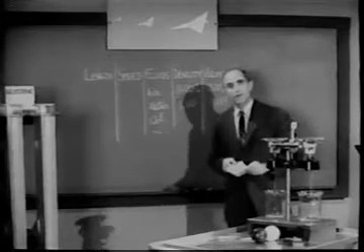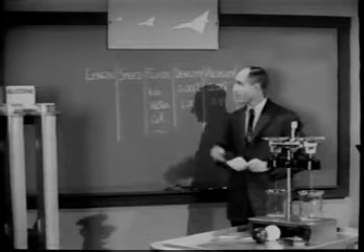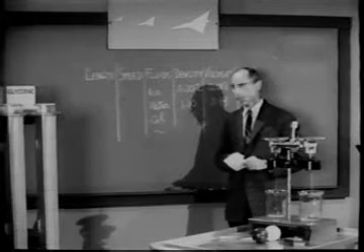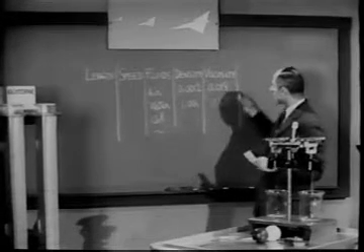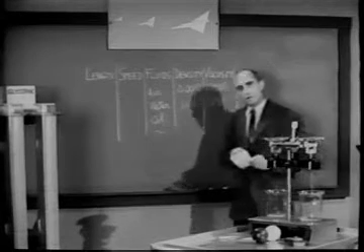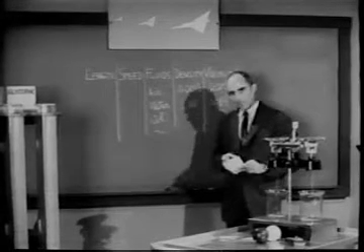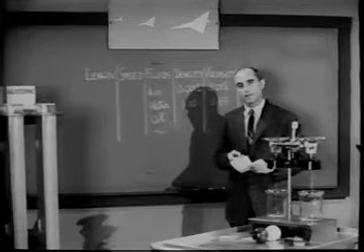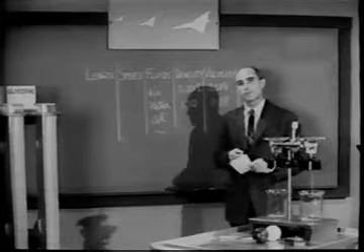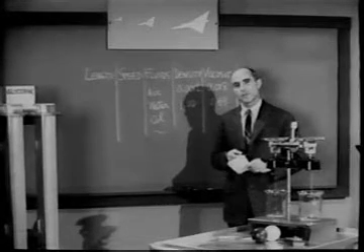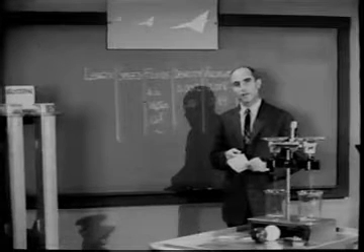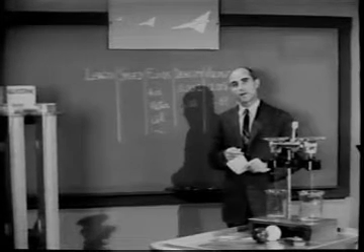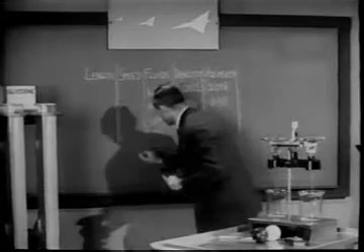All the experiments of the series would appear to be very different from each other, and in general they are unrelated. But consider a special situation. Suppose that in two of the experiments, the several quantities in Newton's force balance bear the same ratio to each other. Then those experiments are dynamically similar. And from the point of view of mechanics, they are in a sense identical experiments.